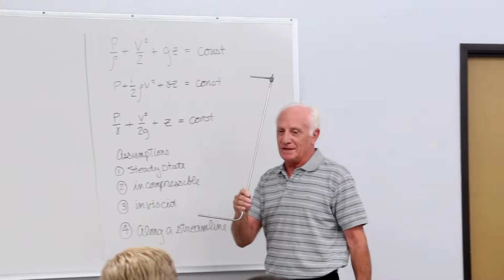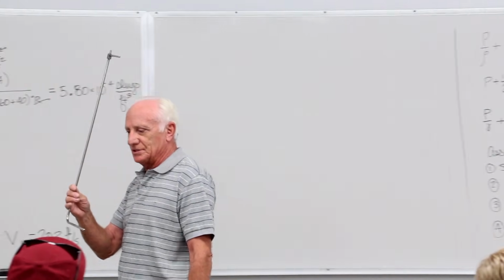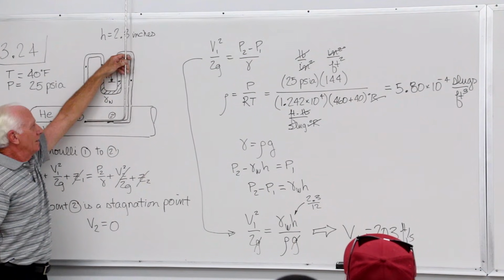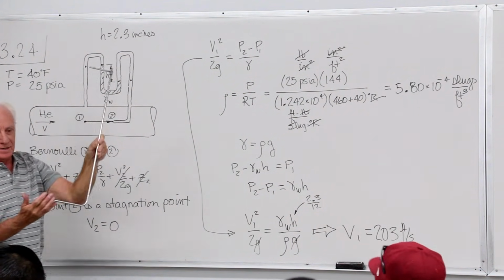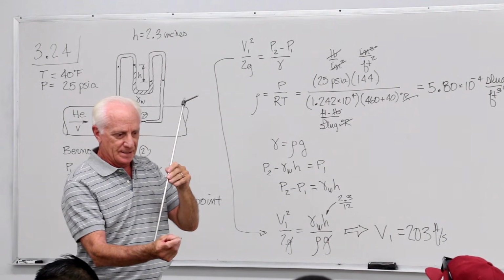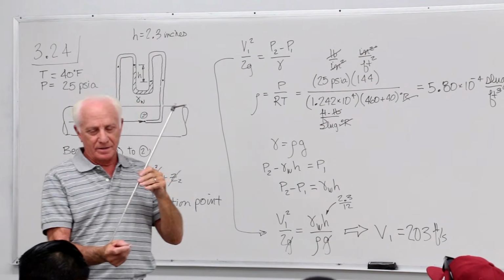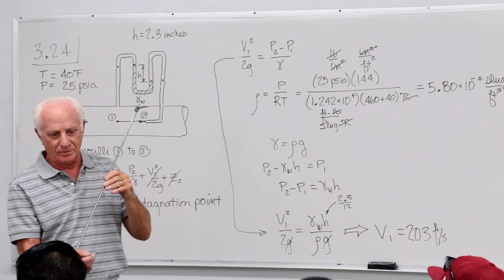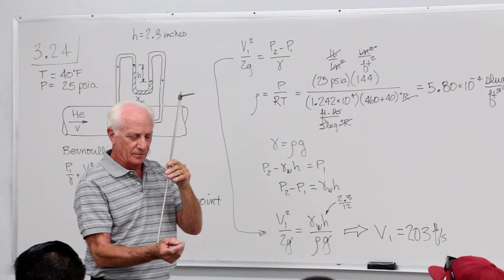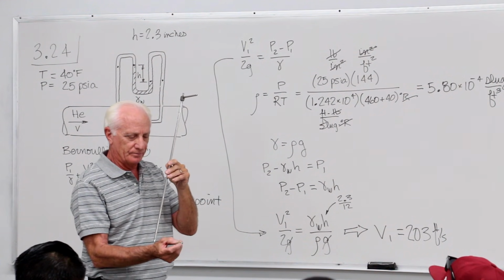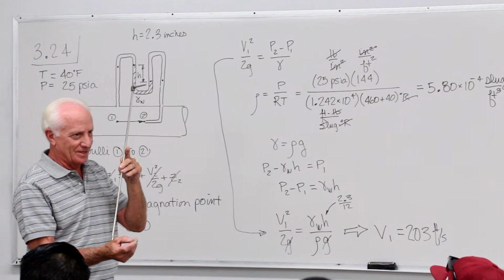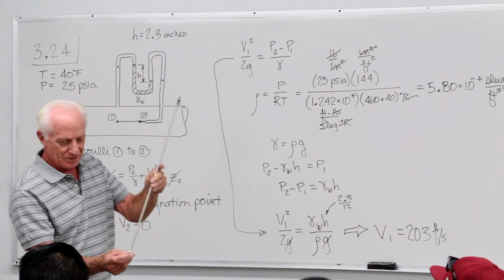This is a pitot-static tube. You put that thing in a pipe like that. In the front, there is a hole in the nose of the tube. That's a stagnation point. Like in front of your car, there's a stagnation point where the velocity comes to 0 near the grill. On a missile or an aircraft, there's a point in the front where the flow comes to 0 velocity. I don't care if it's a bus, there's a point in the front where the velocity is 0. That's a stagnation point.